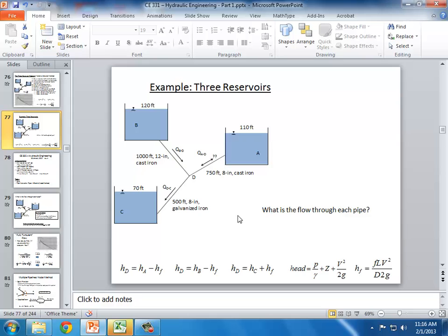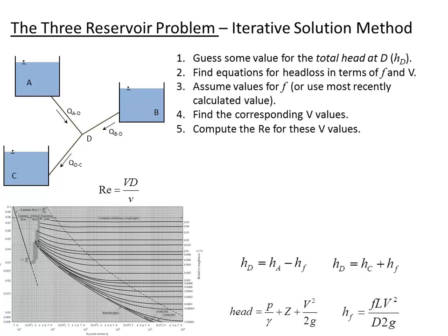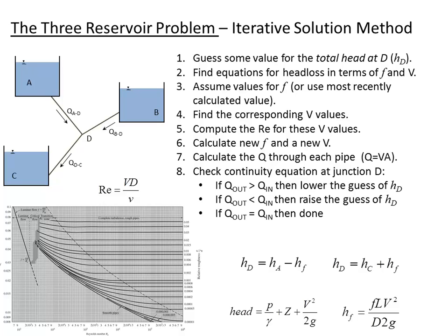All right, so we've got the relative roughness, and my suggestion was that we take a look at the Moody diagram and guess that we're in the fully turbulent range. So let's look up 1.3 times 10 to the minus third.